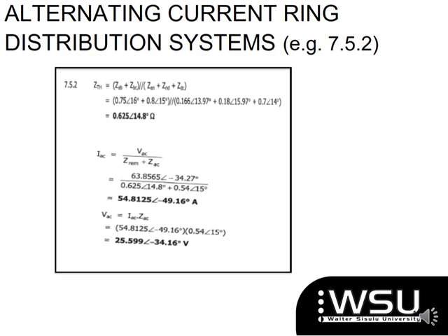All right. So I would advise you guys, so that you don't confuse yourself with the repetitive VAC, that when you do the Thevenin equivalent with this interconnector in 7.5.2, once you found the Z Thevenin, then you go to your IAC, all right, and you say, don't say it's VAC, say it's your V Thevenin, and you divide by your Z Thevenin plus my ZAC that they give you.